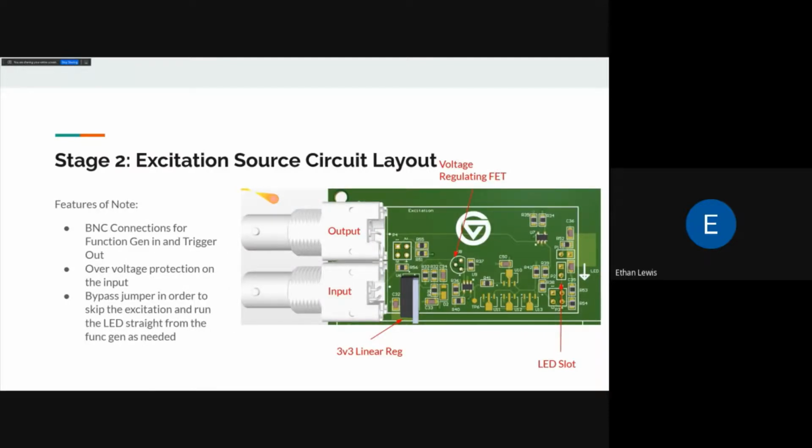Here's the board layout for our excitation circuit. One thing to note is that we included a 3v3 voltage regulator because the comparators need their own 3v3 source.